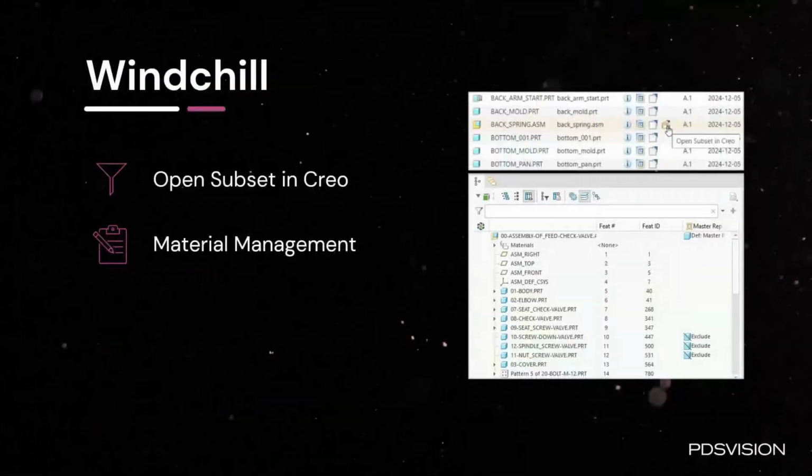Finally then, Creo 12 makes it slightly easier to work with Windchill assemblies, or assemblies stored within Windchill. You can now open a subset of components directly from Windchill without needing to predefine a simplified representation in Creo Parametric. This lets you quickly access just the parts you want from an assembly, which will improve performance and load times.